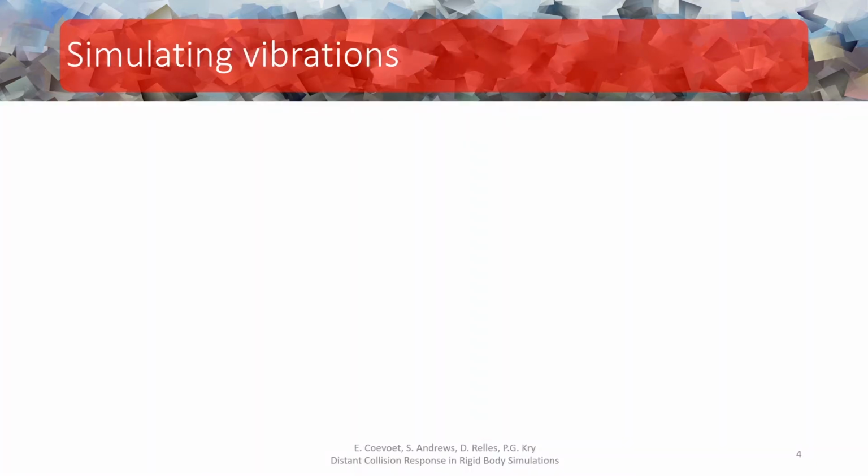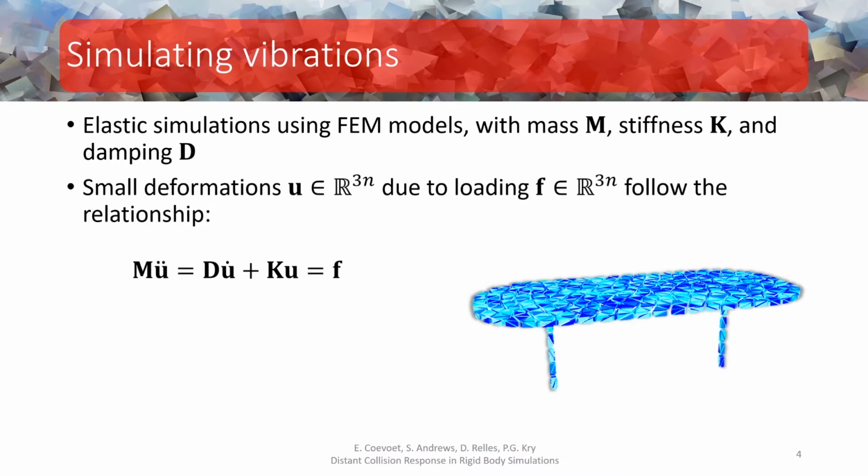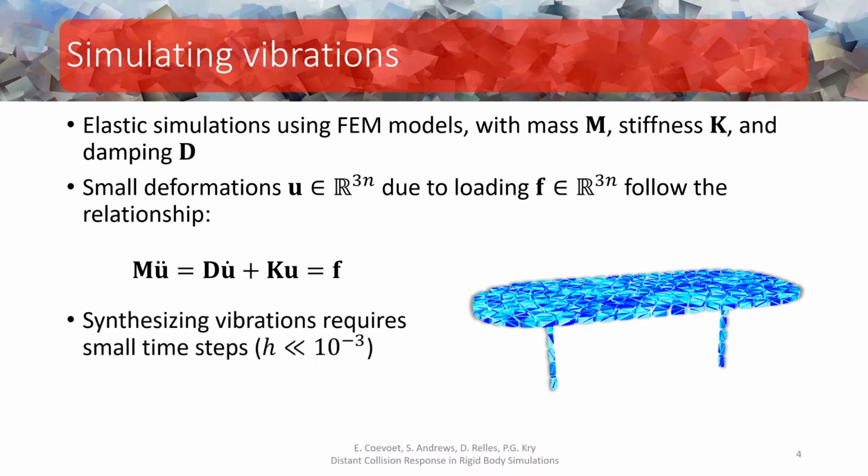Typically, if we'd like to simulate vibrations due to impact, a detailed elastic model is required. Assuming small deformations, a linear elastic model involving the mass, stiffness, and damping of an FEM mesh could be used to synthesize vibrations. However, to faithfully reproduce the high-frequency vibrations that occur in stiff objects, very small time steps are necessary. And even for linear elastic models, they are prohibitive for real-time applications such as video games and interactive VR training simulations, which we target in our work.